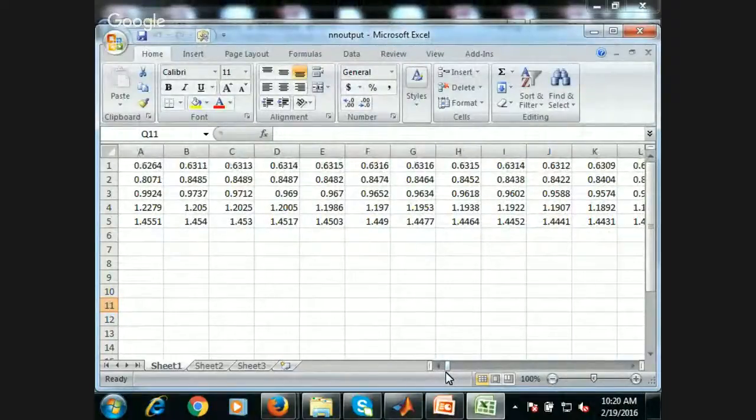We had a multi-level inverter. Our problem was we have to find out the 5 angles for each H bridge such that my THD is 0. So I wrote my equations, and those equations I solved using any method, Newton-Raphson or GA or PS, or any method. I found my optimal angles, and now I have a set of angles. Now my input is modulation index and my outputs are my firing angles. I have kept both of them in 2 separate files.